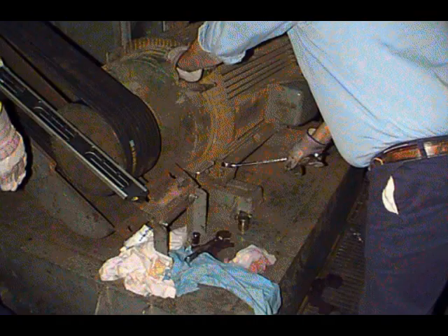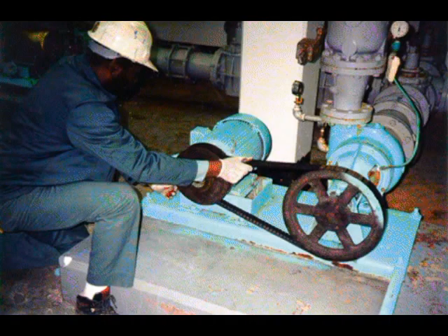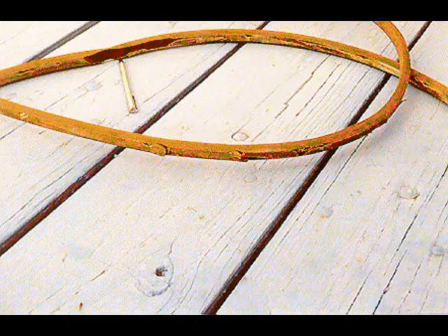After a few days of operation, the belts will seat themselves in the sheave grooves. At this time, you should readjust the belts as required. The belt drive is now properly tensioned, and only occasional readjustment for groove wear will be required. It is important not to adjust the belts too tightly, as this could cause problems like bearing overheating and excessive belt wear. Squealing, glazing, fraying, or other signs of wear and tear are indicators of belt problems.